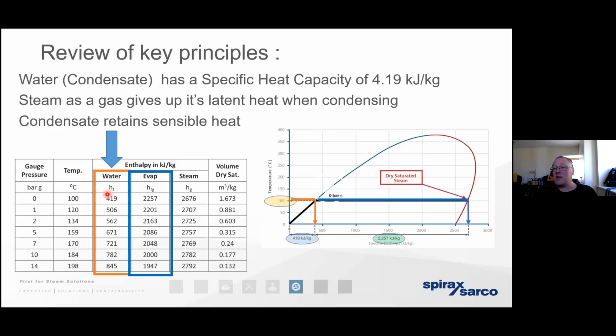For one, we've got the inefficiency, the heat loss. We get a reduced mass of steam finding its way to the process, extension to the process time. The steam that does find its way to the process is going to be significantly wetter. It's going to have less energy contained within it, causing the process time to extend further still. We get the maintenance issues.